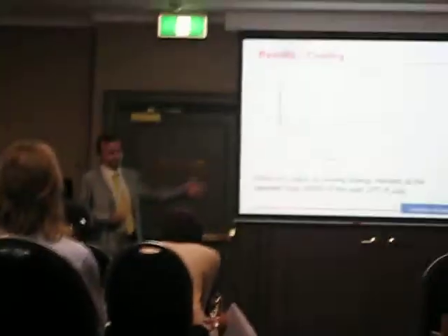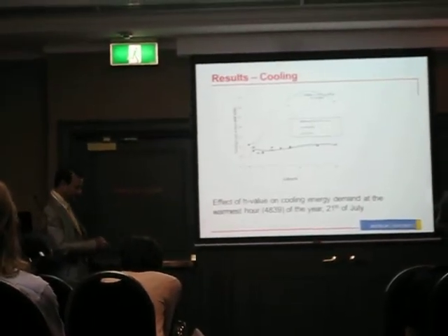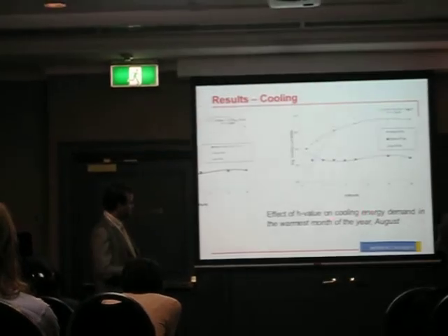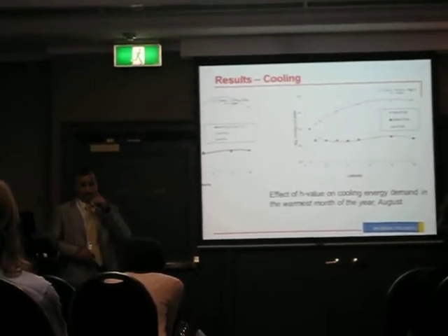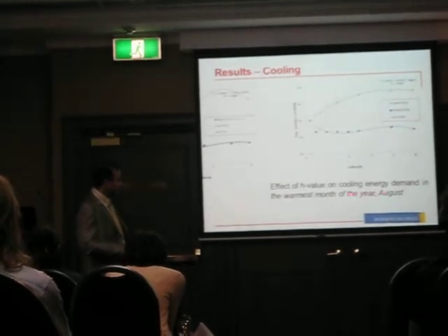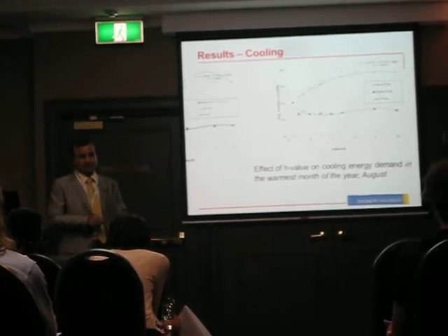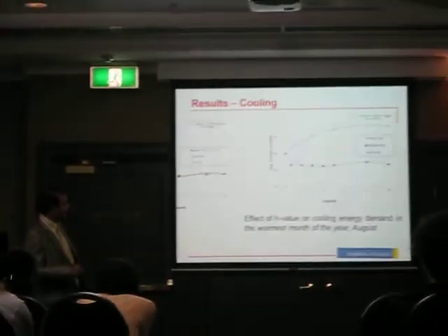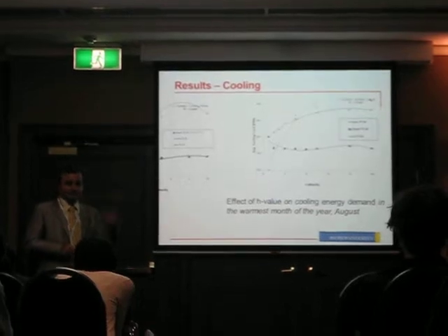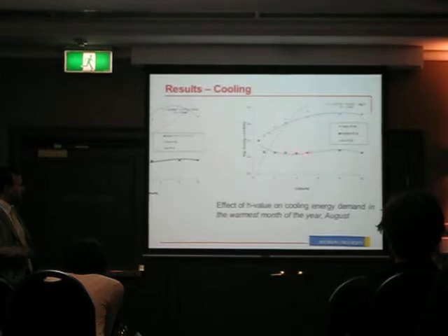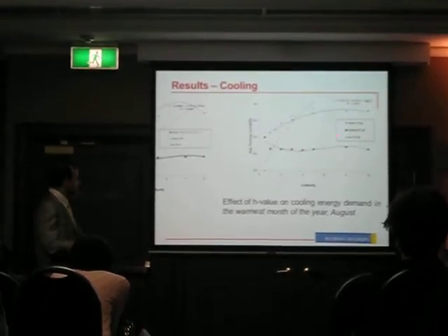This simulation is drastically fast. But with PCM, I checked 1 hour. I started with the hottest time, and then checked the cooling energy consumption in August, which is the hot season in Toronto. And as you see right now, there is a gap between 10 millimeter and 1 millimeter. Of course, as a minimum, PCM is a mass, so thermal mass can make it possible to need less energy. Of course, we have to pay for PCM.